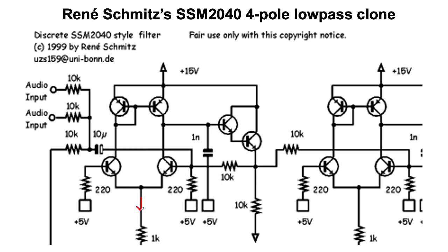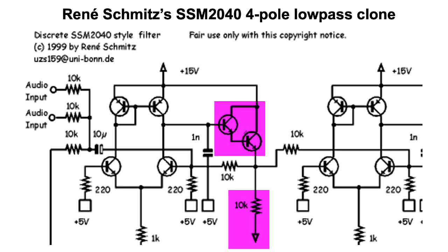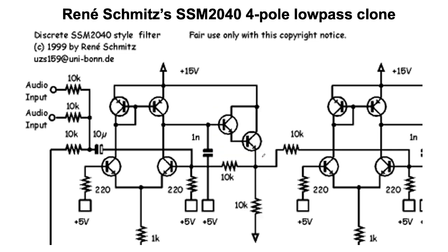We need current sinks instead of current sources the way we would for something like a 3080 or a 13700. This is forming the voltage buffer. This set of 2 transistors is called a Darlington configuration, and basically these 2 BJTs are acting as a super duper extra awesome BJT. So if you just think about that as a single BJT, when I'm combining it with this 10K resistor down to the negative voltage rail, this is acting as an emitter follower. It's acting as a voltage buffer.